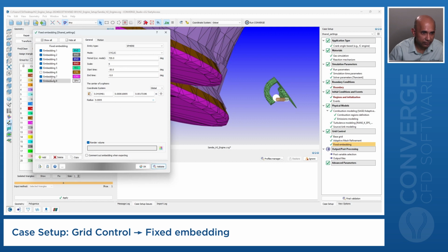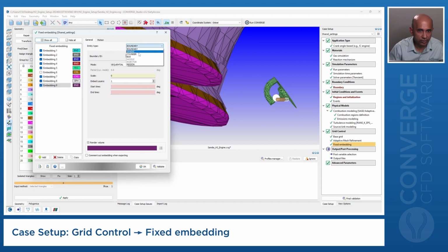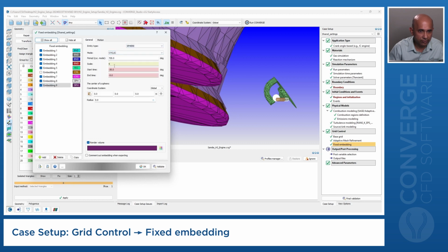And then in the same location, I want to add another sphere, again cyclic, level 5. In this case, that's down to 1/8 of a millimeter, starting at -30, -5, same vector, but the radius is 1 millimeter.